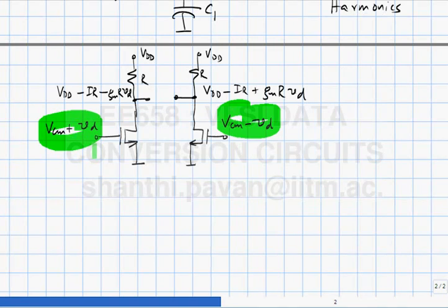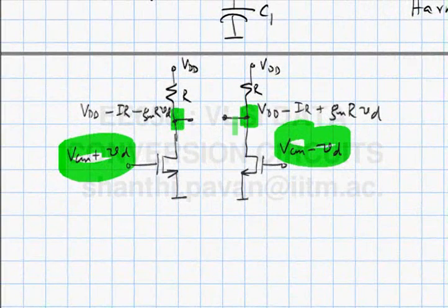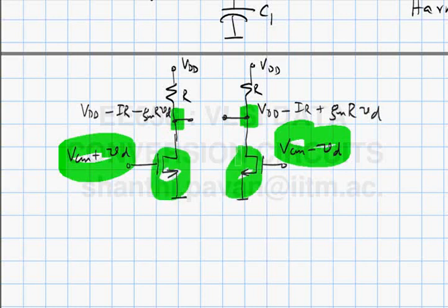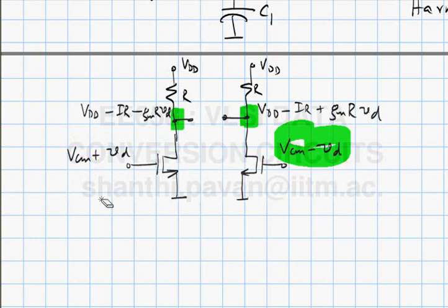Then we see that the bias current in the transistors increases a lot, which causes a large change in the output voltages, which could potentially cause these transistors to go into the triode region, causing the gain to reduce dramatically. And the culprit, as we have seen in the analog circuits class, is that this way of biasing a transistor with a gate source voltage is a very unrobust way of biasing the transistor.